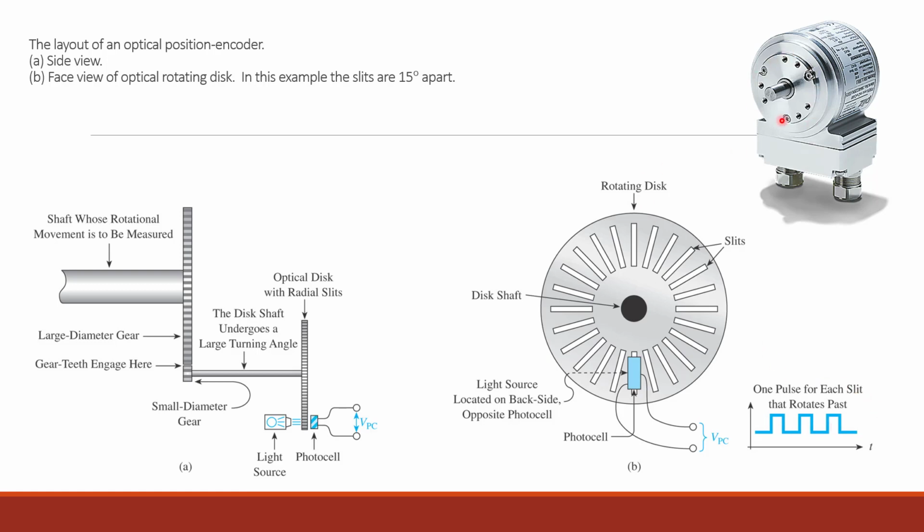Another application of this is using it as a tachometer, because if I know how many degrees I'm rotating against time, in other words, how fast these are coming, if I can get 360 degrees in 1 minute, then I have 1 complete revolution per minute. That's 1 RPM. So if I'm counting these pulses to get my degrees, and then timing them, now I have RPMs, rotational speed.